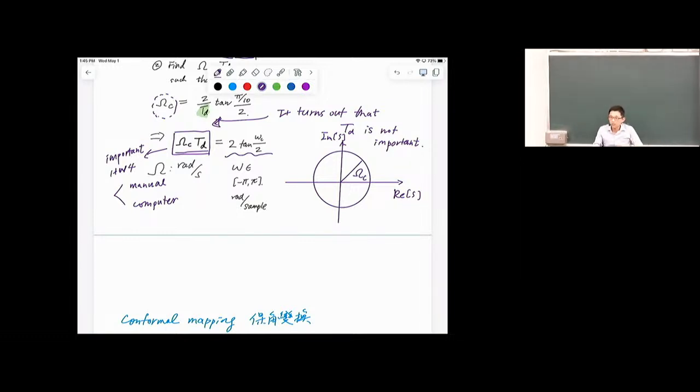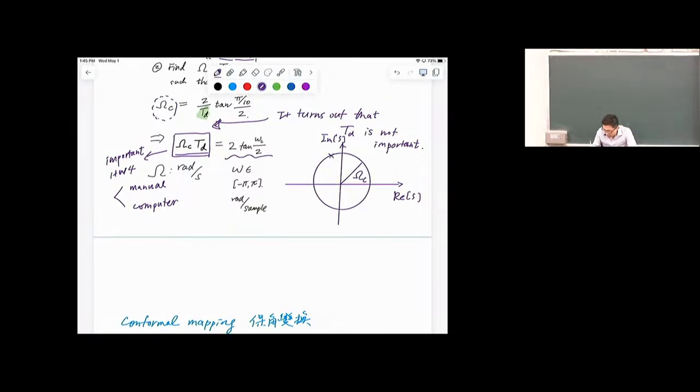So Butterworth filter design involves something like cutting pizza, just equally placing poles. For example, if n equals 6, then we equally place 6 poles. That's the order of your filter. You equally place them on a circle in the S domain, and then write down your analog prototype.